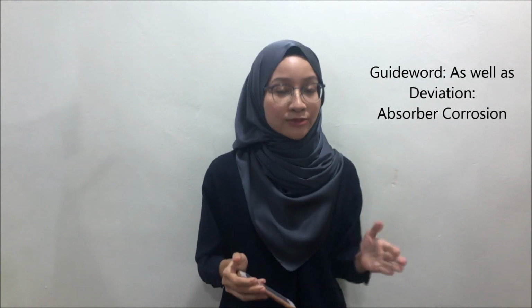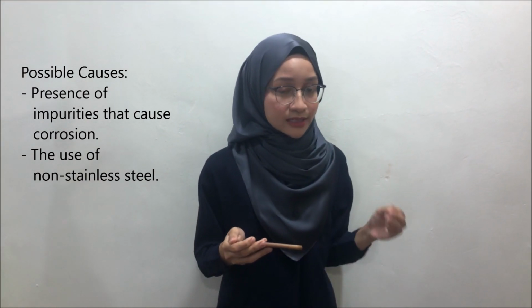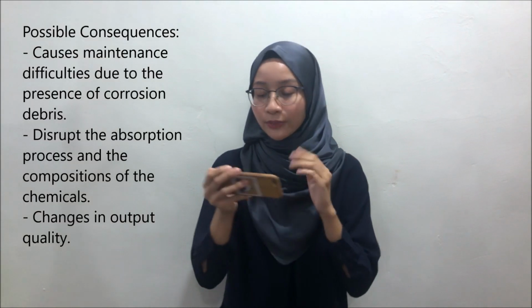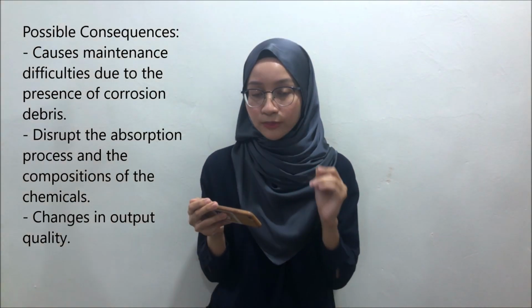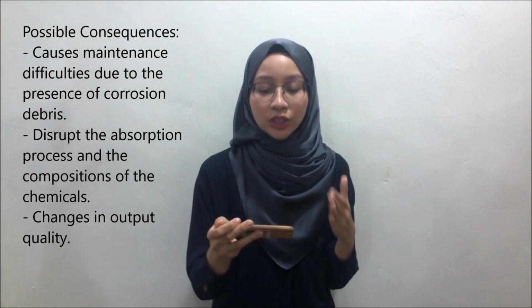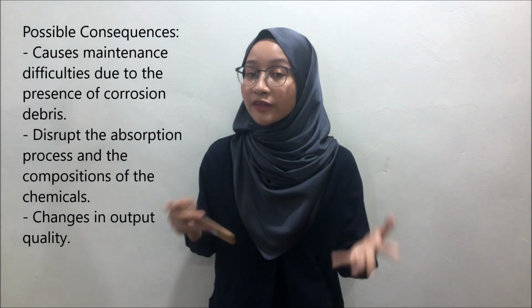The last process parameter that we have found for our project is the fifth one, which is corrosion. The guide word for corrosion is as well as, and its deviation is the absorber corrosion. Absorber corrosion happens due to the presence of impurities that will cause corrosion, and also it is due to the use of stainless steel. It will lead to maintenance difficulties due to the presence of corrosion debris in the absorber column. It also will disrupt the absorption process and efficiency, and also the composition of the chemicals.